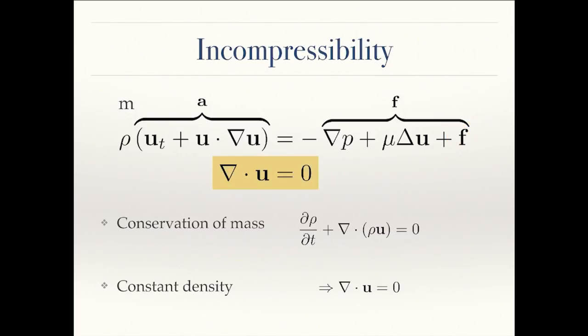Okay, so we've talked about the first equation, which is F equals ma, or conservation of momentum for the fluid. The second equation really just came about from conservation of mass for the fluid. Before, we saw conservation of mass; we actually derived it quickly, and it had this form. If the fluid is constant density, then that first term is 0, and we can also pull the density out of the second term, and it just reduces to this simple form, which is the divergence of the velocity field u is 0.